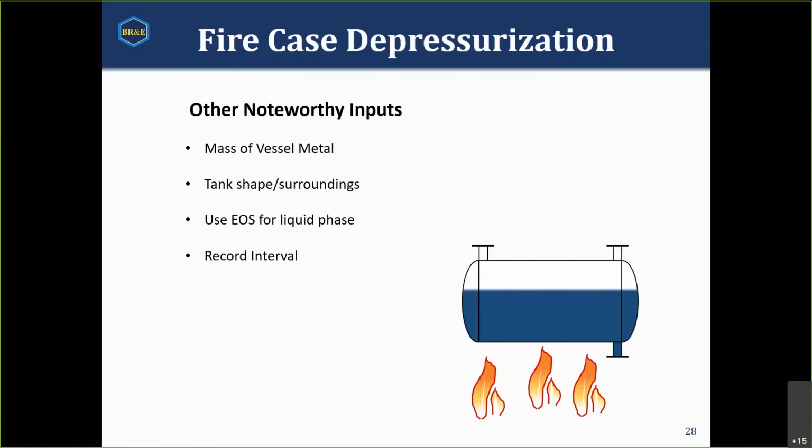There is a toggle at the bottom of that tool for using the equation of state for the liquid phase. What that means is whatever equations you are using to do your calculation in your system, it will use a standard equation of state to calculate your flashes. This is important if you're doing something like an amine system and you have an electrolytic model in your liquid phase.